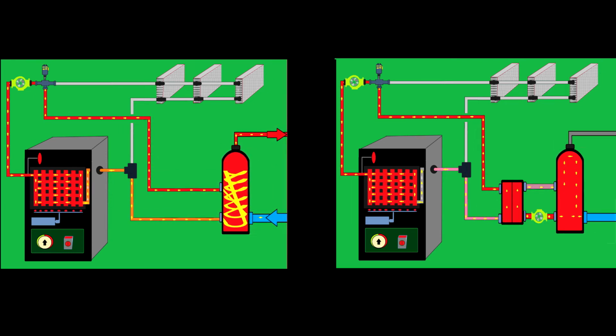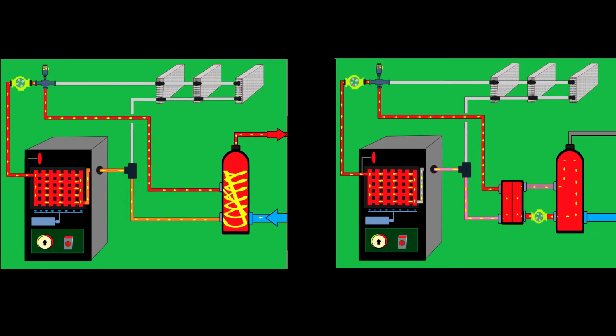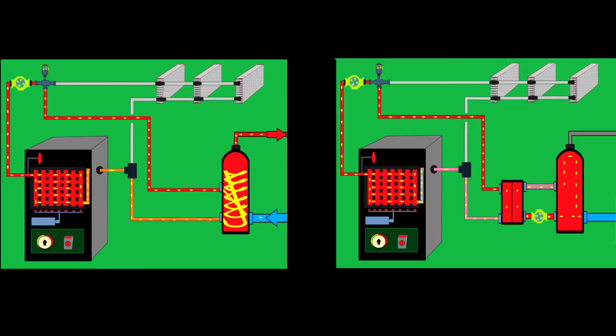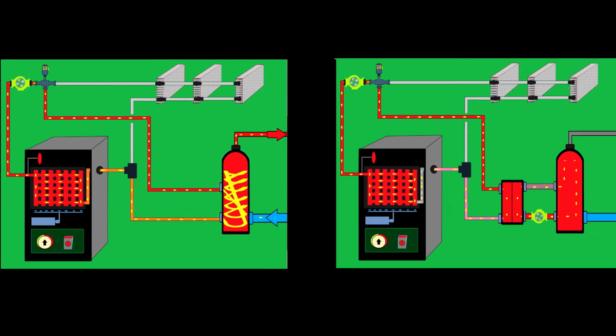Looking at the right hand side, you will see that you have a heat plate, and this plate heat exchanger allows the domestic water to pass by, and also allows the heating agent to pass by. So the heat exchange will happen outside the cylinder. That cylinder doesn't have inside any coil, absolutely anything. So this is the difference between these two types of system. Just watch and try to understand.